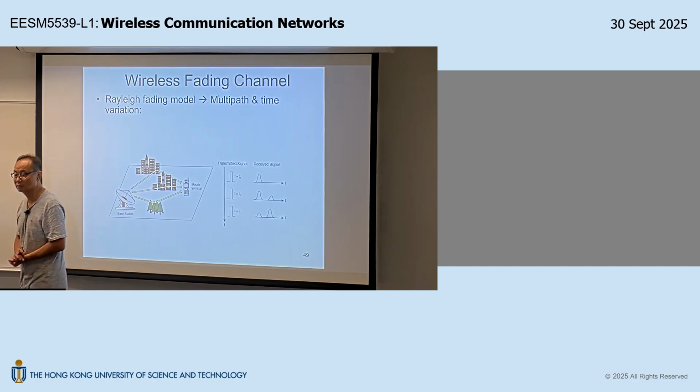Ignoring all the constants, you immediately see that this is inversely proportional to distance squared. So let me ask you again, what's the physical reason why the received power will get weaker and weaker in radio propagation in deep space? You see in the explanation, this is a vacuum, so there is no resistance. There's nothing conducting in the vacuum. Still, you have this loss. So why? This is simply because the transmit power, or transmit energy per unit time, is spread over a bigger and bigger surface area. As simple as that. And it turns out that the surface area scales like distance squared.